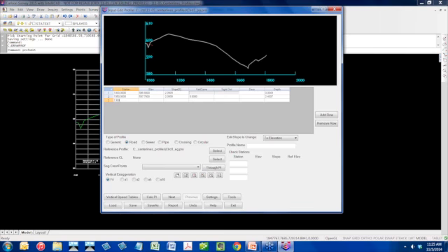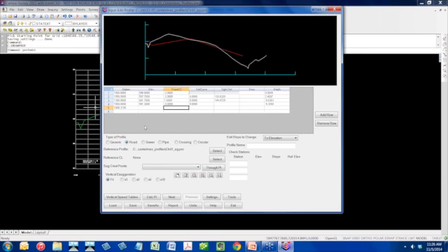All right, my next one is 1300 is my station, and the slope out is going to be a positive 1.6% going up. My next station will be 1650, slope minus 3%. And then my last station is going to be 1808.31 and a 1%. So that's where I'm going to end up.